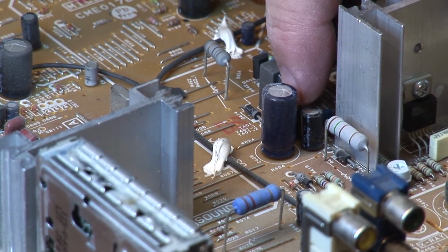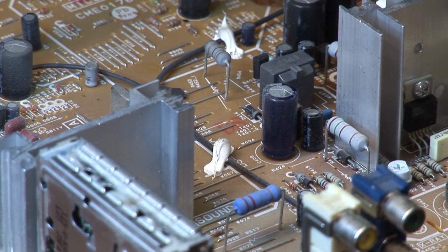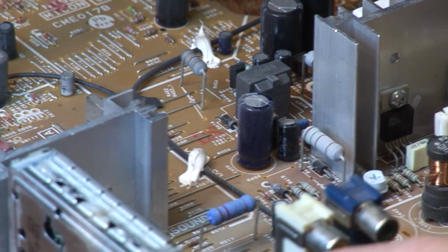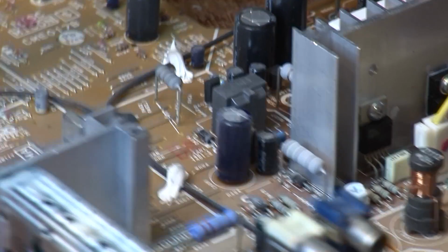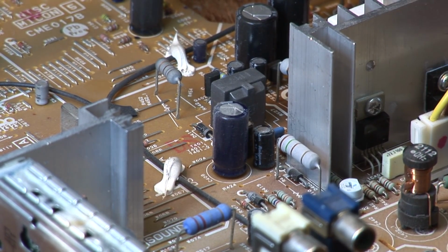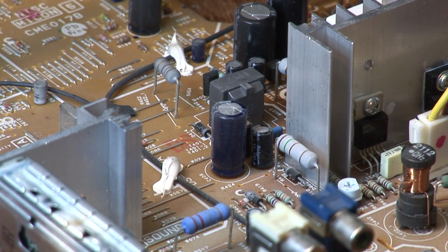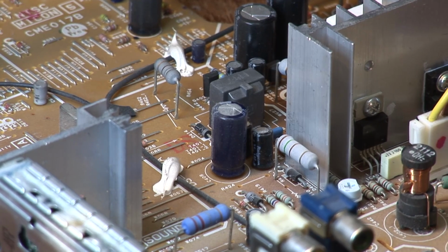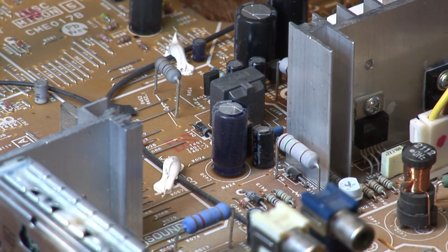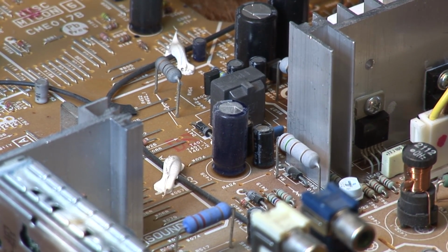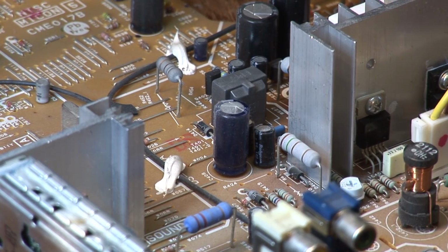We'll check the ESR on that capacitor there and see whether that is the culprit. More than likely it is these type of vertical fold-over problems. It's typically a small capacitor. It's called the bootstrap capacitor. Anyway, let's check the ESR on that capacitor and replace it. We'll see if that fixes the problem. But we'll check the ESR first.